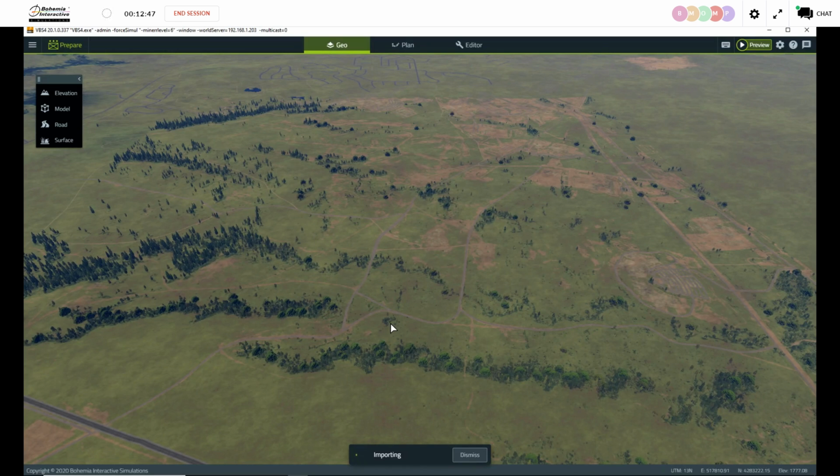But if you remember yesterday, if you were attending the intro sessions, we actually flew over to Kingsville, where we'd used ultra high resolution texture to map onto the terrain. And you could do the same thing anywhere on Earth. If you have the geo-referenced image in the GeoTIFF format, which is exported by many different GIS applications, you can import that directly into VBS Geo.